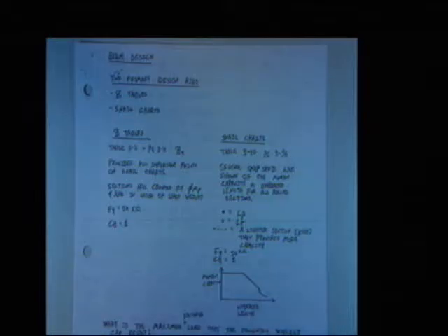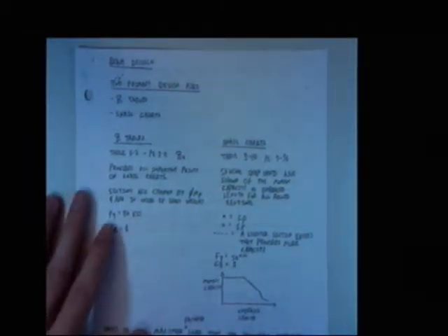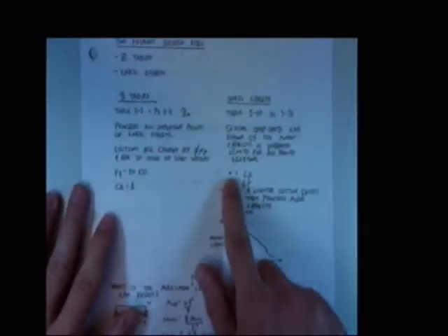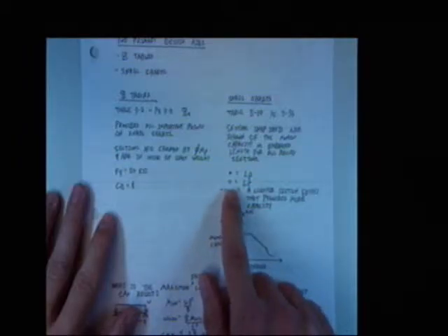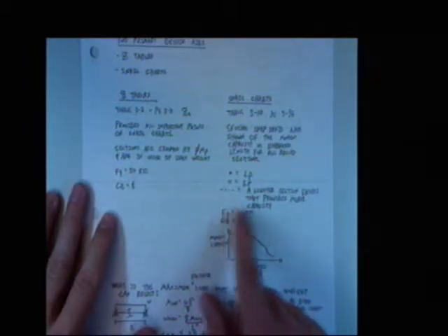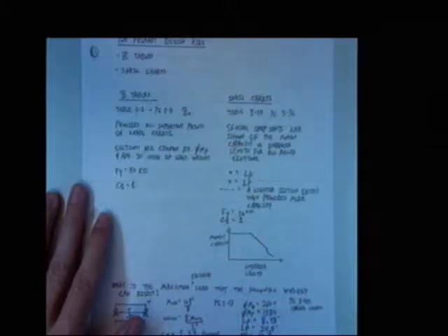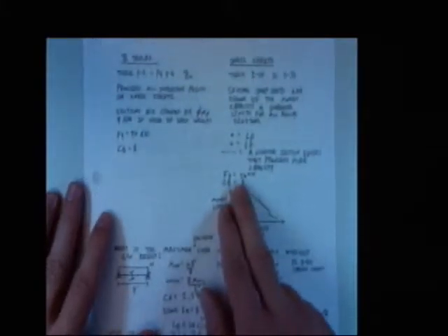Several snapshots are shown of the moment capacity versus unbraced length for all rolled sections. L sub P's are closed dots. L sub R's are open dots. Dashed lines mean a lighter section exists that provides more capacity. Everything's derived for an Fy of 50 KSI and C sub B of 1.